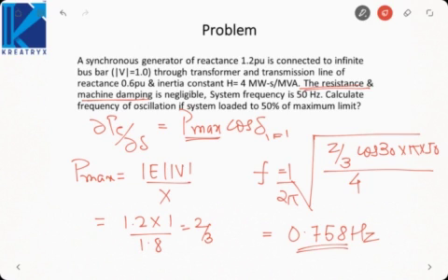Okay. So remember, the formula that we derived was for omega. If it is asking frequency, you have to divide omega by 2π. So do not leave the last step, because otherwise all your effort will be wasted. You may be applying the right formula, but do check the units in which it is asking the frequency. If frequency is asked in radian per second, you will find omega. In hertz, you have to find omega upon 2π. Let us move on to the next problem.